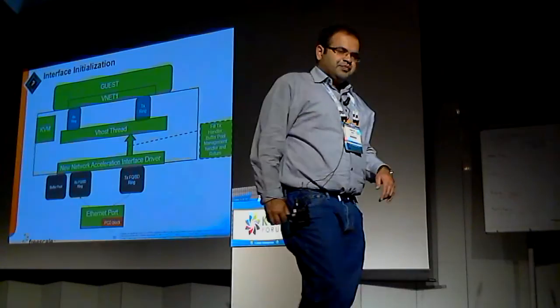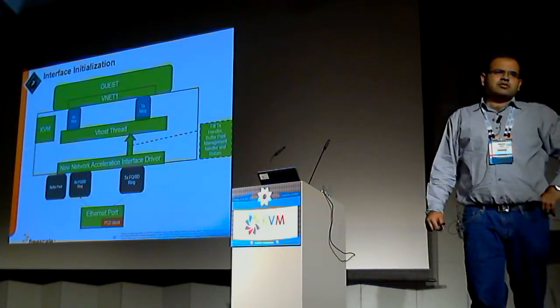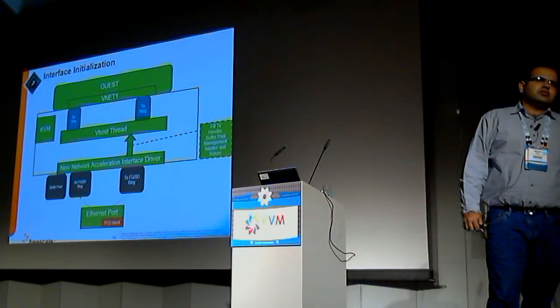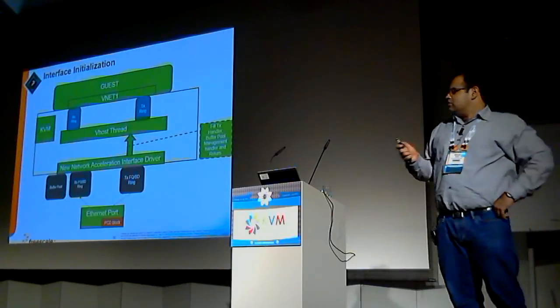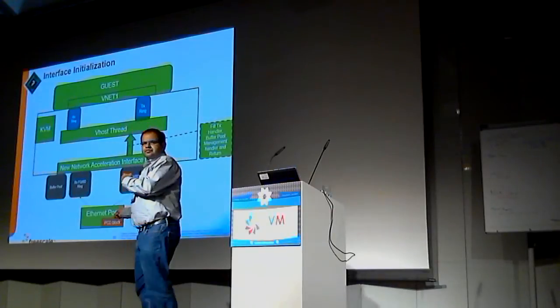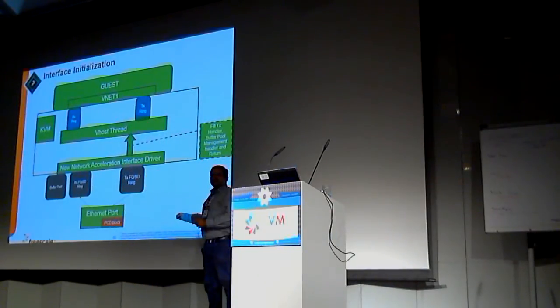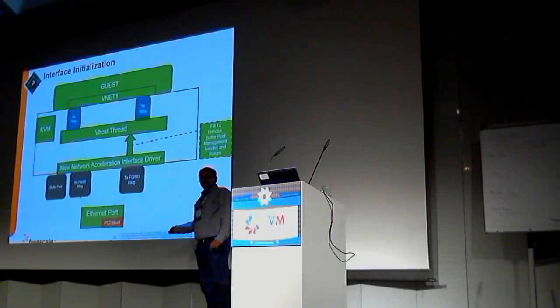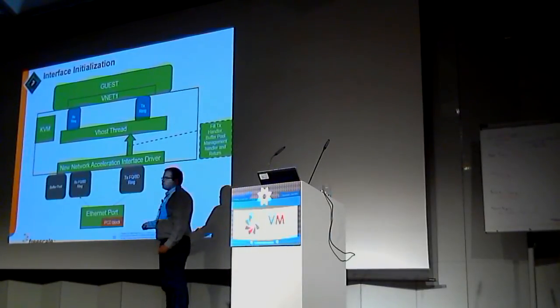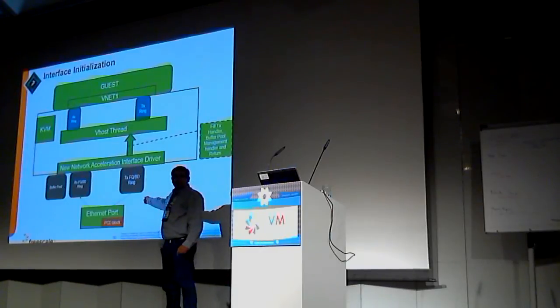This slide makes it look like you're essentially dedicating an Ethernet port to a given guest. No, not the port. It's actually this particular frame queue. This port can cater to multiple queues. You have this parsing, classification and distribution logic in the Ethernet port, which allows it to distribute packets to multiple frame queues, and each frame queue could cater to a different ring in the guest.